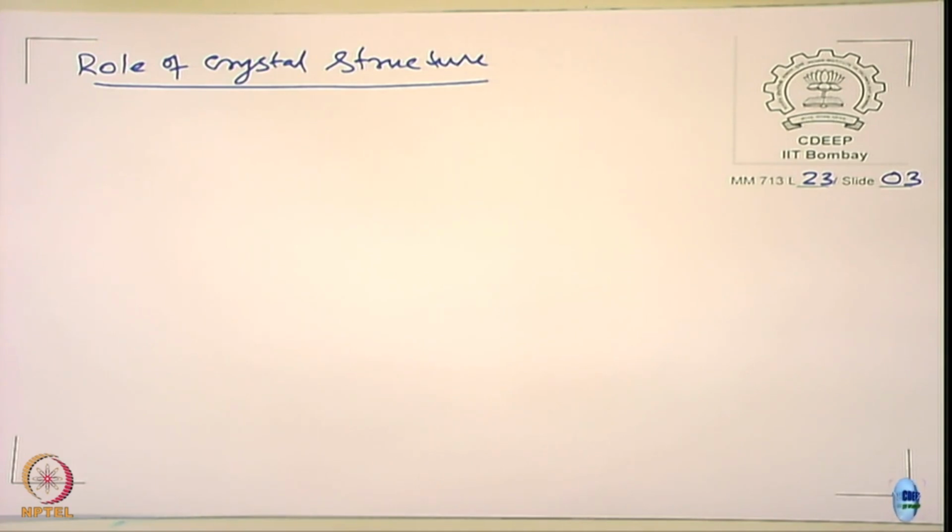We saw earlier we classify stainless steel as austenitic, ferritic, martensitic, duplex and precipitation hardening stainless steels. By nature the precipitation hardening stainless steels do not have very high carbon content, the carbon content is very low. The strength of that stainless steel comes from where? Comes from the alloying elements, right, like aluminum and copper, they form precipitates, they give rise to strength. So, the carbon content of that is very low.